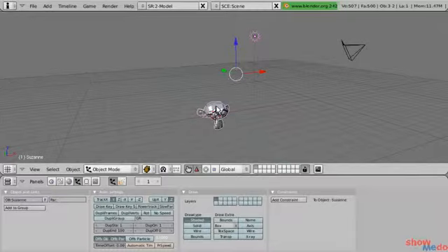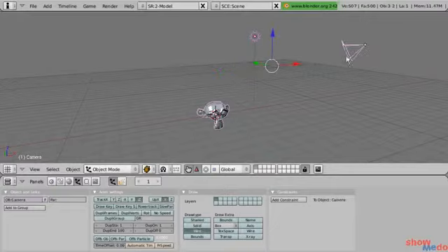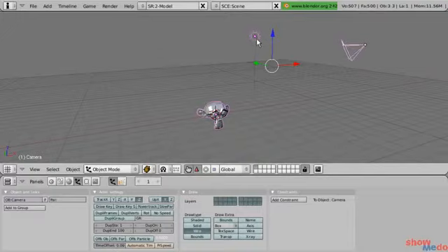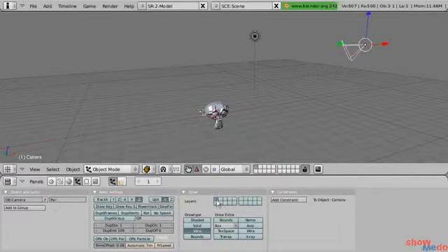Another trick you can do is if you select multiple objects, you can select multiple objects by Shift and right-clicking on them. And then if you press M, you can set all of these objects what they're going to be on. So I'm going to set these 3 objects to be visible on all layers. Click OK, and now you can see they're on those layers. Otherwise, if I was just going to use these buttons right here, I have to set that for every single object.